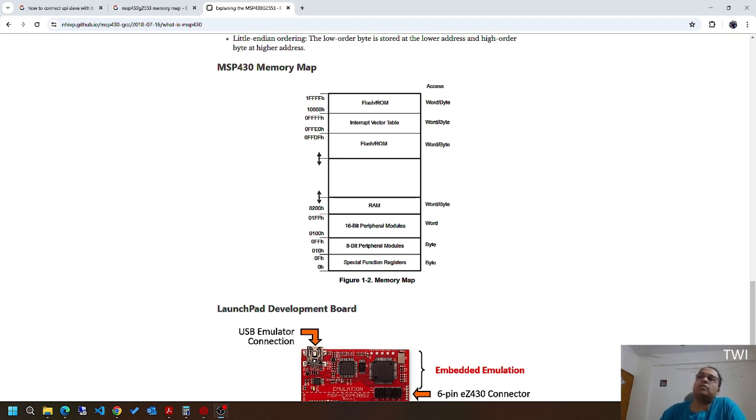Now coming to the actual core of it, this is done in some categorized steps. The first step is to check in an online web portal or a cloud service whether a new version of the firmware is available. If you're releasing a new firmware or patch, once a new version is available, it should be able to download the firmware and check its integrity, using a CRC or any kind of computation. After the integrity is valid, you can replace the old firmware with the newer firmware, and then proceed with the boot.